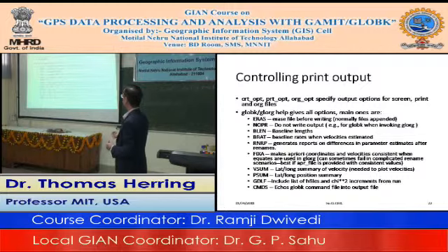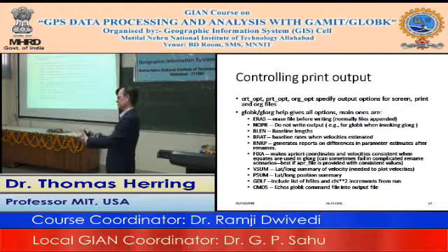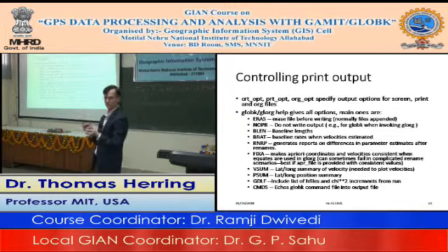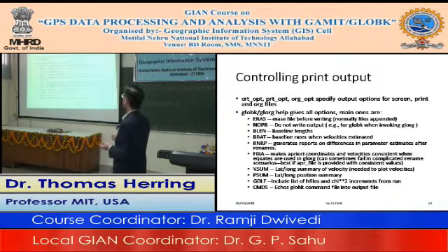RNRP generates reports on the differences in the parameters when you rename. So when you have a site, you change it, you say it could be a different position because I changed the antenna. This RNRP will give you the actual estimate of the change and the uncertainty of that estimate based on the full covariance matrix as you go across. Fix-A is a way to fix any problems, most of your problems, in the APR coordinate systems if you are doing equating of velocities, etc.